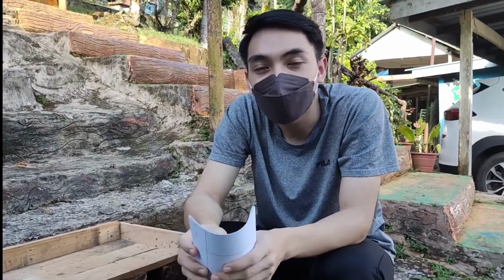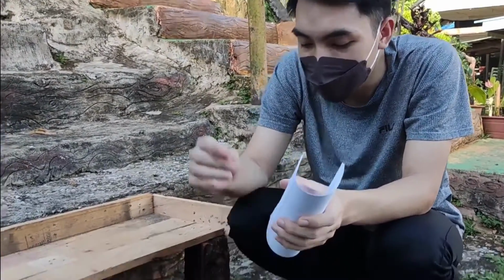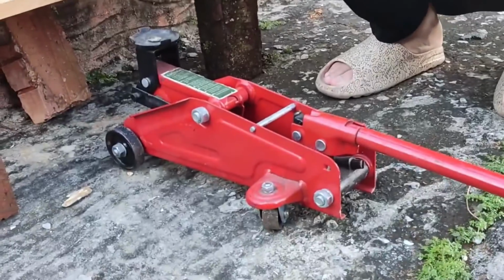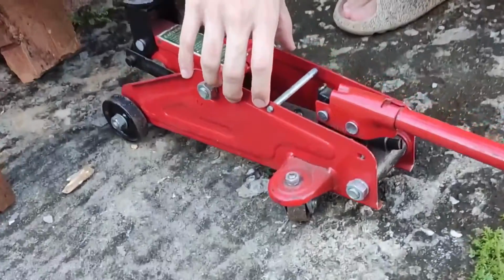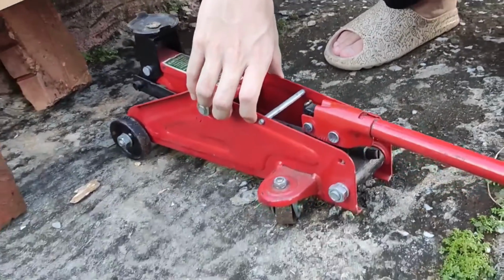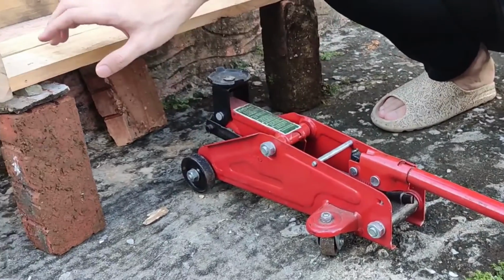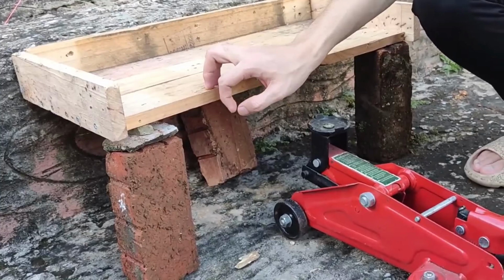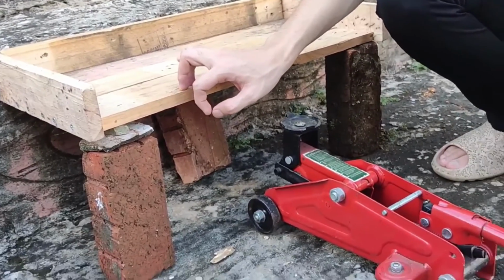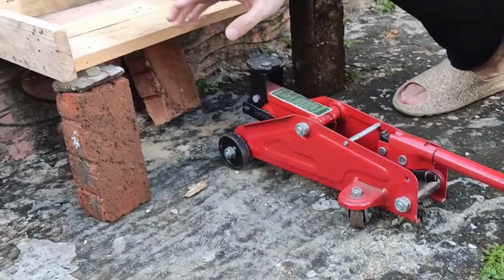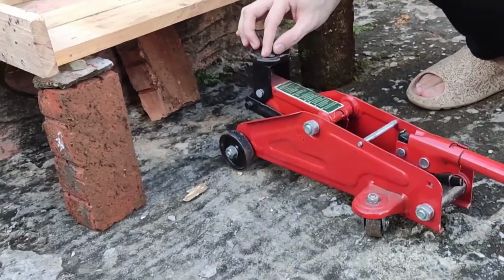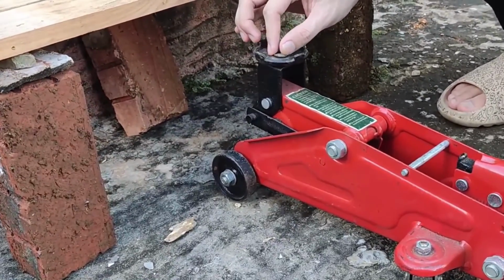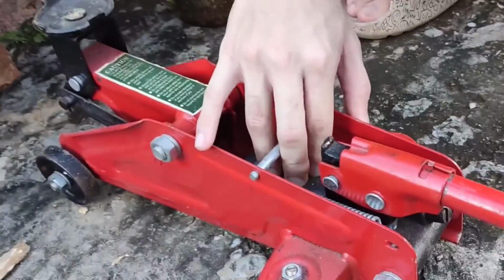Before I go into details about how to do the measurement, first let me briefly explain to you guys about this machine. First, in the normal PLT apparatus, we will have the load indicator. It will show you how much force that has been applied onto the rock sample. Then this is the conical platen where the rock sample will be held. Inside here, this is the hydraulic piston.